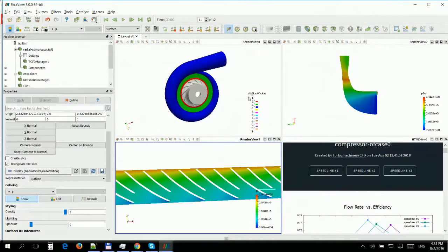So in OpenFOAM, in any CFD, I'll start from the beginning. In any CFD, especially in OpenFOAM, you never start from scratch. You always need to grab something which is working, which is similar to your case, and modify it. That's how it works. That's how people get results. If anybody is interested in simulating a compressor, do the following.